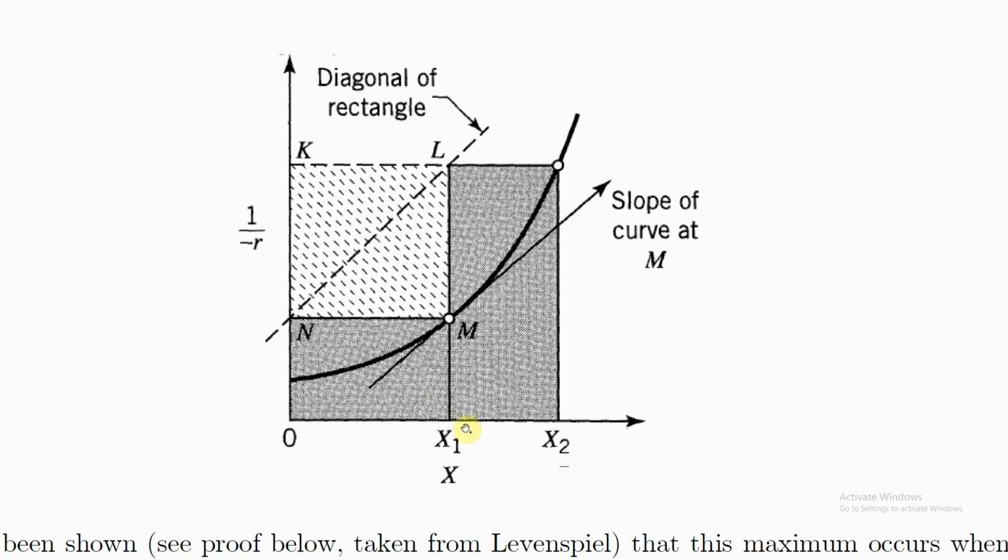So let's say we've chosen x1 here, then that fixes for us that this is the point x1 is operating at, and hence this is the volume of the first reactor. And then, of course, we still have to do a second reactor, and in that second reactor, we have to get to x2. So this is then the volume that we have to build to get to that required final conversion. So as we choose different values for x1, that changes the total volume of the system.